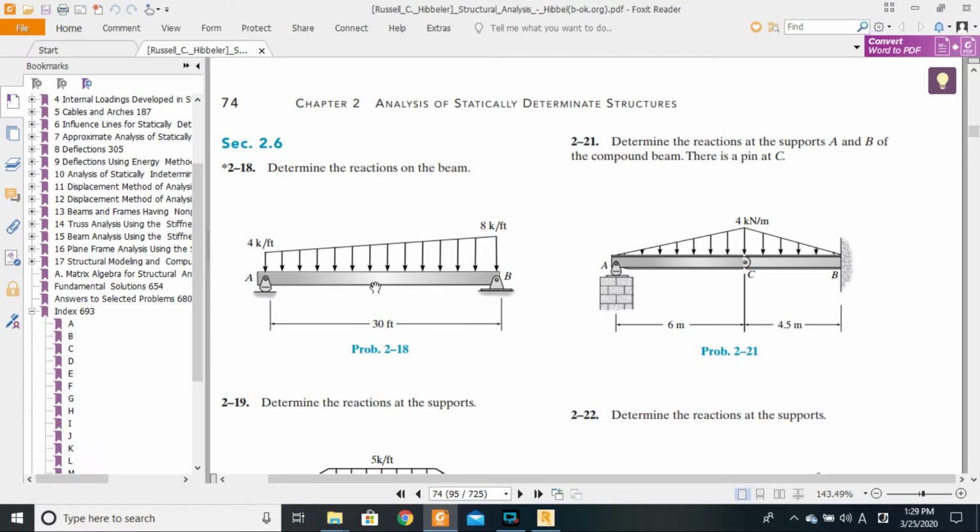if I have a system like this system here, it was just one beam. In this case, I have a discontinuity at the level of the pin. So I need to separate it into an element this way and an element this other way. I'll need to draw two beams, so I'll need to create a node here. This node will allow me to model a pin at this level. If I just do it as one element, then it might disturb at some point. This discontinuity needs to be represented.